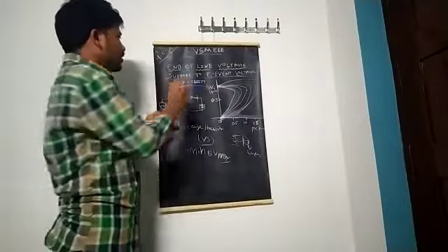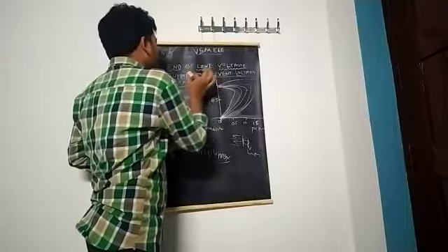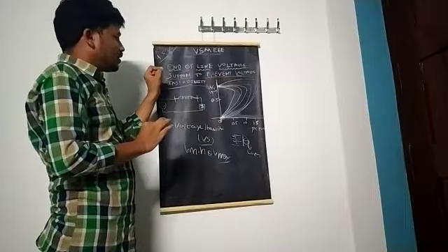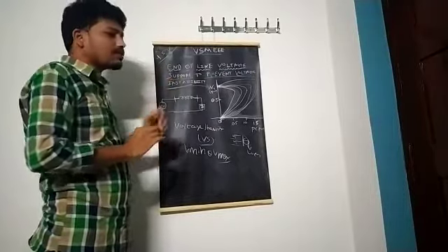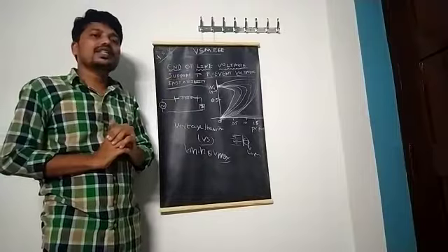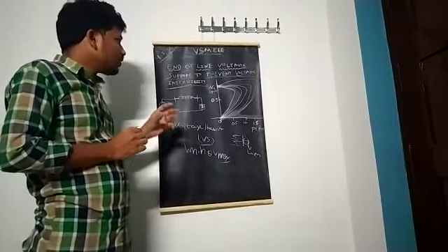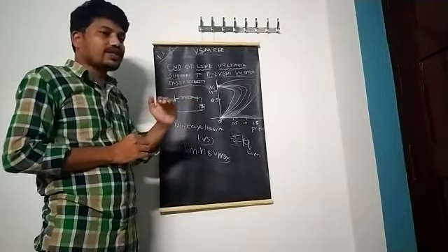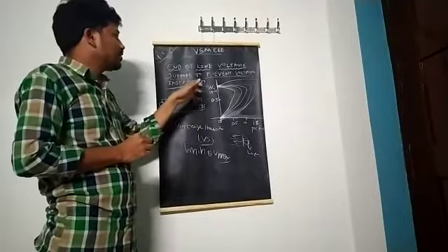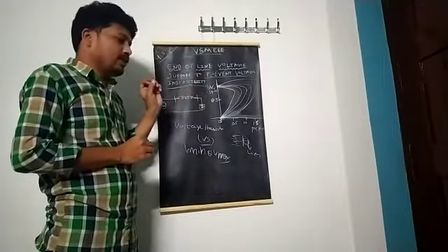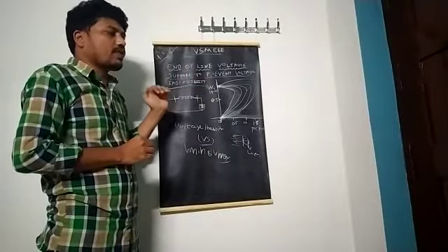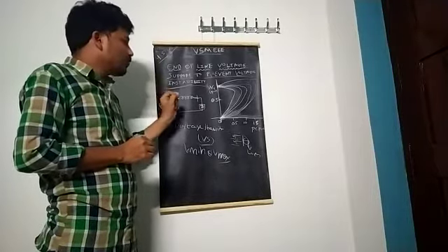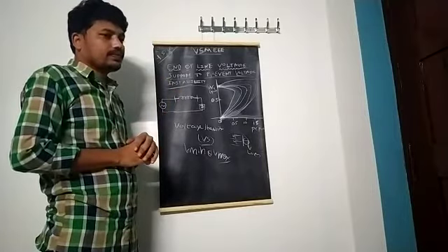But here our topic is end of line voltage support. Why are we connecting the compensation technique at the end of the line? Because in the radial transmission system, voltage stability issues, that means voltage instability or voltage imbalances, occur especially at the end of the line. To prevent this voltage collapse or voltage imbalance, generally at the end of the line we connect a compensation device. Is it clear?